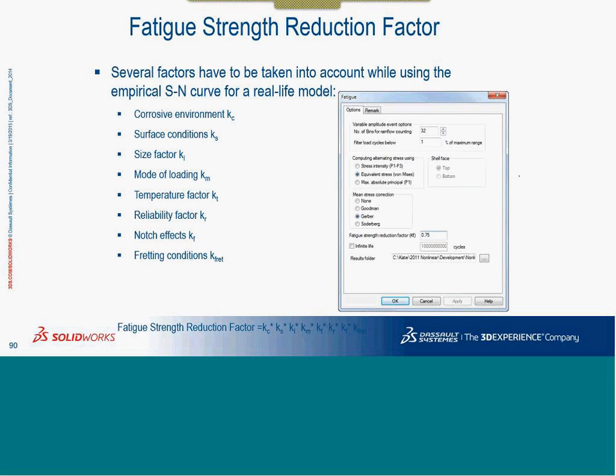When the size of the component goes up, typically the manufacturing details change and it can lead to a different kind of fatigue. There are also factors like notch factor and other things. Typically, when they do the practical testing, the temperature loading may not be there. There might be vibrations. So all such n number of different factors are accounted for by only one simple factor, which is called the fatigue strength reduction factor.